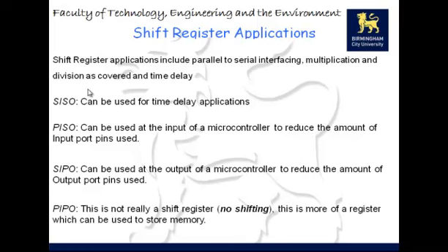of output pins used. PIPO, parallel in, parallel out, is not really a register. There's no shifting occurring there. It's just a simple memory device, really, just like a register that we looked at before. Okay, by no means is this an exhaustive list of applications of shift registers.